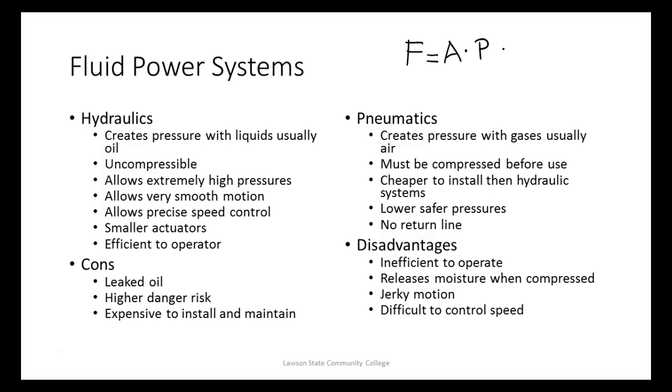If I take that 1 pound of pressure and I push it against 2 square inches of area, I would create 2 pounds of force for 1 pound of pressure on my fluid. That makes sense? So when we do hydraulics, we create a pressure with what? Liquid. Usually a what? Oil.